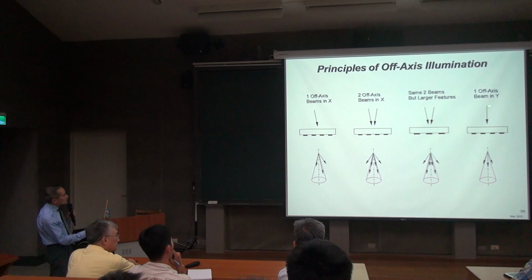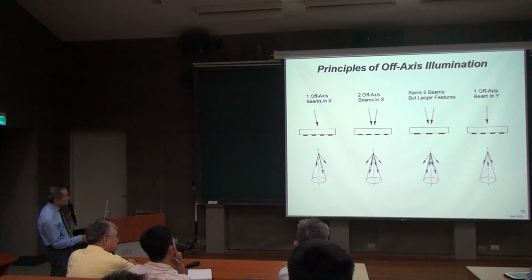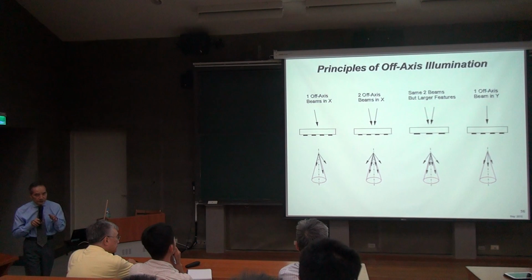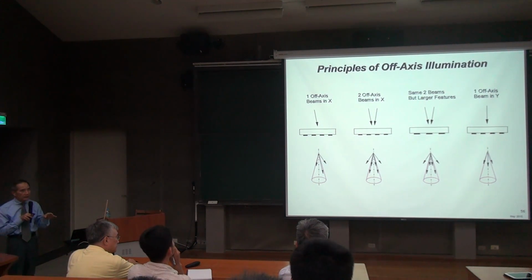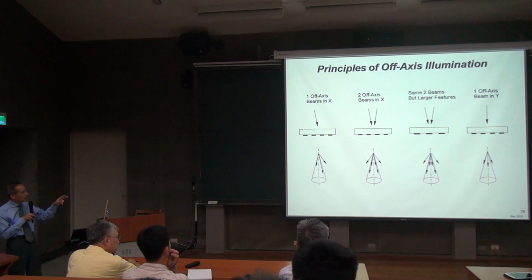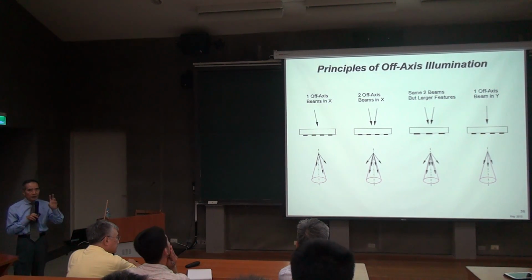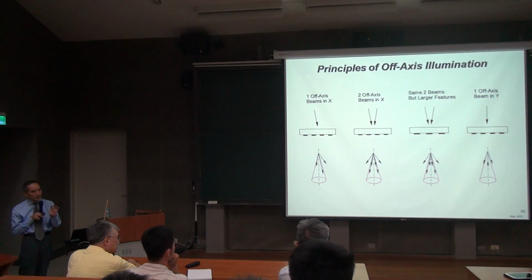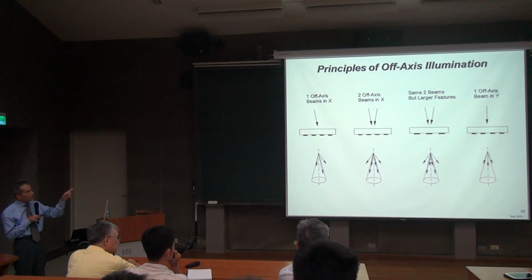Now, if you tilt this, it will shift all these 3 beams this way. Now your 2 beams will be accepted by this lens and resolved by this lens. You are using these instead of that, so you are doubling the frequency. Again, with a half micron line, now you can use it to resolve a quarter micron line. And also with this, you don't have to worry about phase conflicts in the phase shift mask. So it's also very powerful.